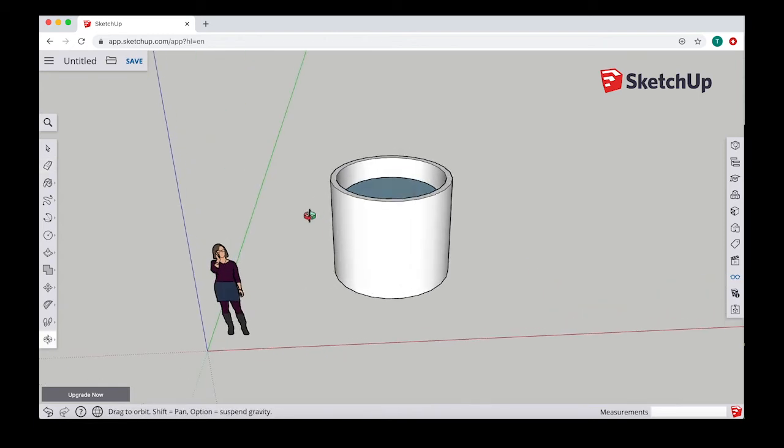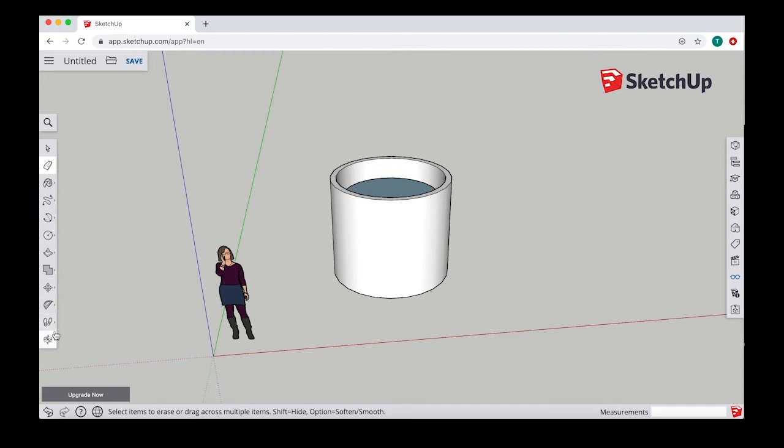Next, we'll look at the labels tool. This can be found again in the tape measure menu, and it's just a box with A1 in it. You can click on this, and you can label anything in your model space. If you click on a face, it will create an arrow to that plane or edge or whatever it is, and then click again, and you can change whatever this label is. So if we just wanted to label this as a cylinder, we could do that. Make sure when you finish writing that you click outside of the box to complete it.